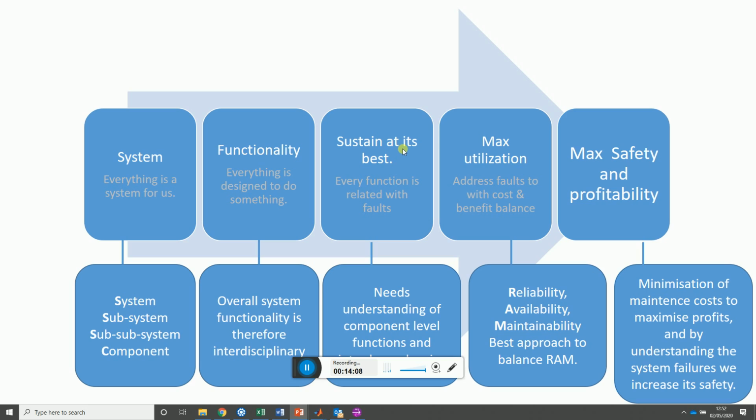And so to do that, we need to understand the overall hierarchy of the system, subsystem, component, and their possible fault modes. So how many ways can a tire, for example, fail? What can go wrong with a tire? It can get a puncture, for example. It can get friction, and due to that friction, its surface can get degraded. It can get slippery. So all those fault modes we want to think about for all these systems, subsystems and components that can affect this overall functionality.